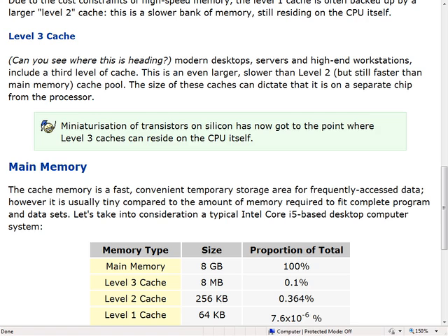You might be thinking, there are like 15, 20 models of each type of CPU. Do they actually make all 15 or 20 as bespoke units? Am I making a 3.2 gigahertz processor now, and then in 15 minutes we'll run some 2.8 gigahertz processors? That's not actually how it works. What they do is try to make everything the fastest, and then through quality assurance along the assembly line, they work out what things don't work properly and what things can't be ramped up to a high enough speed, and all those sorts of things.